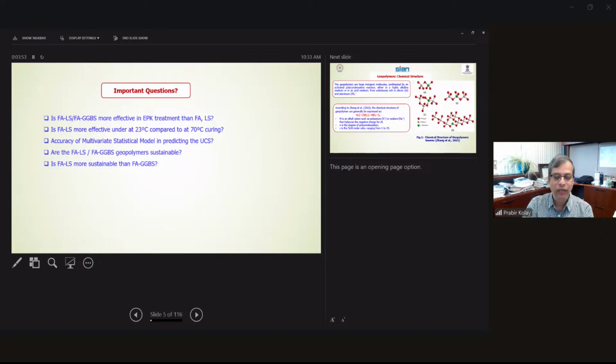The reaction takes place at high temperature, so that is a bit of a practical problem for geopolymers. But here we checked what happens at ordinary temperature, 23 degrees, compared to 70 degrees, since generally 65 to 70 degrees Celsius is used for geopolymers.